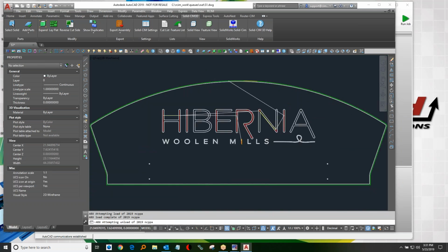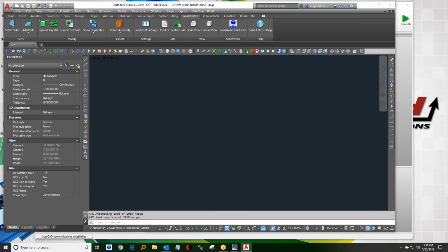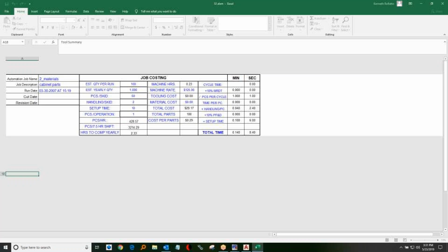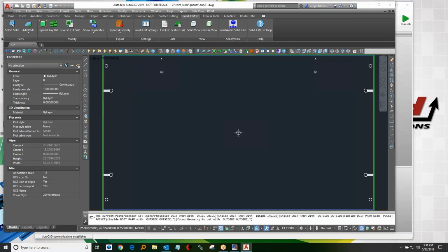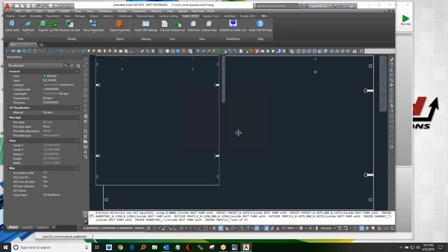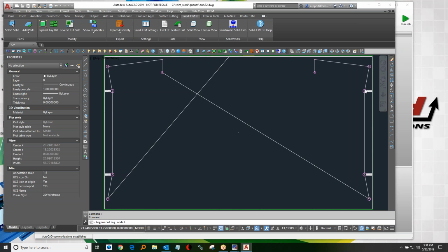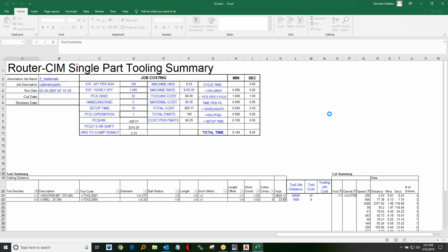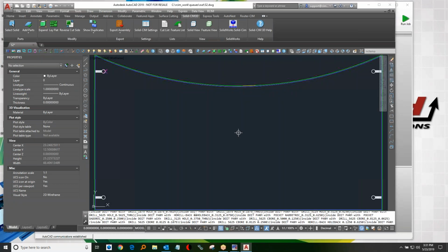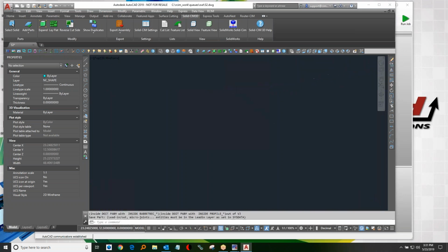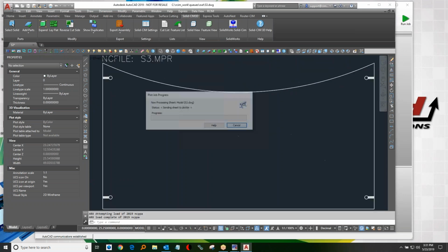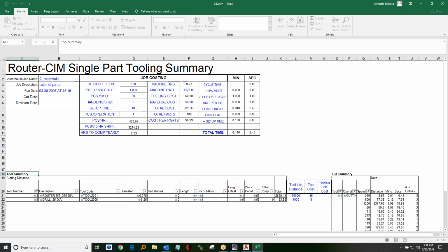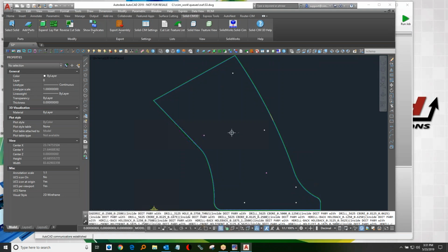I don't know if my tool selected was small enough to go in between all those letters, but what it could do, it did. If not, we're going to need a smaller tool to get in there. We do full 6-sided feature recognition, so we actually recognize the cam lock holes. So if we want to do horizontal operations on those, we can do that on the machine as well. But if I'm nesting, I'm going to skip the horizontal operations for now.